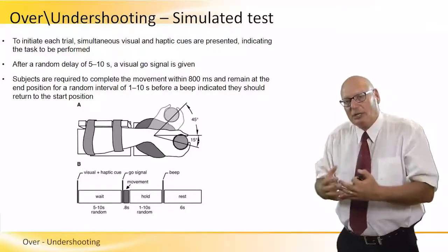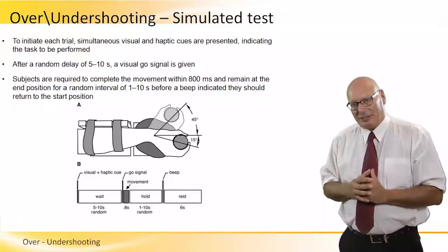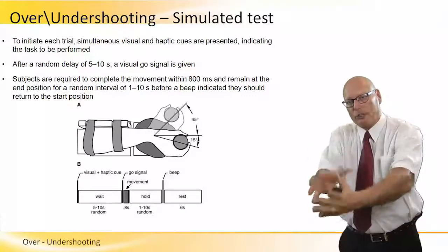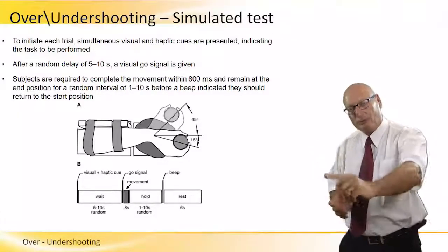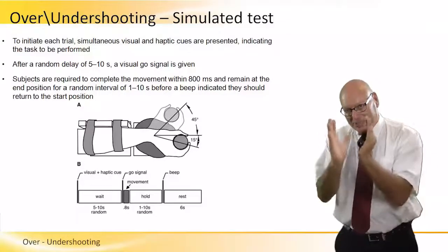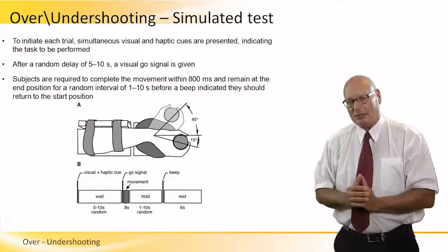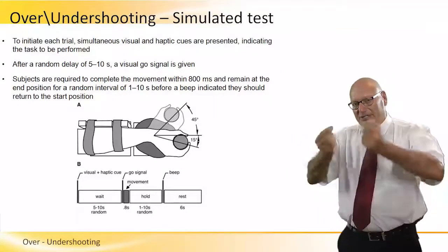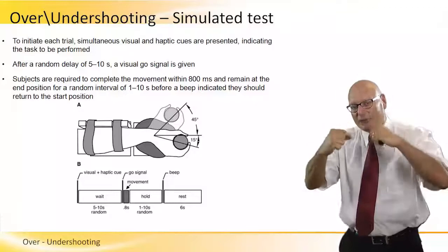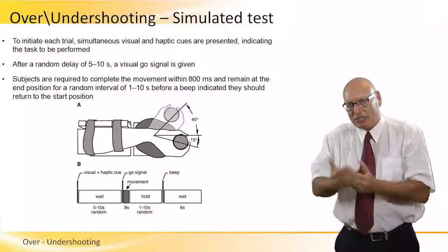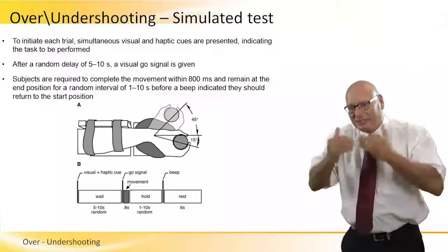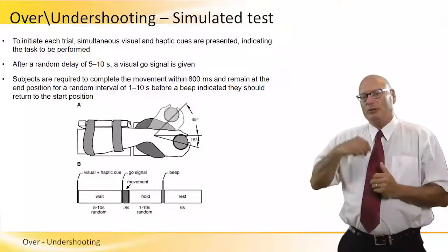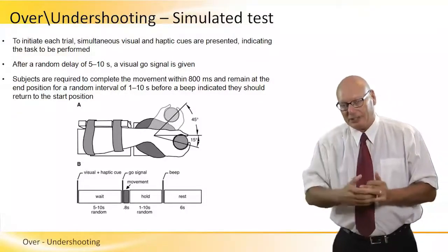Because the robot is an electrical and mechanical system, and because there is an external computer controlling and commanding it, there is what you call propagation delay time. If we still limit ourselves to 800 milliseconds and a beep generation, meaning a command generation, that means just before the finish of the 800 milliseconds, just prior to getting to the 800, we still have to make some decisions in order to assure a soft landing.